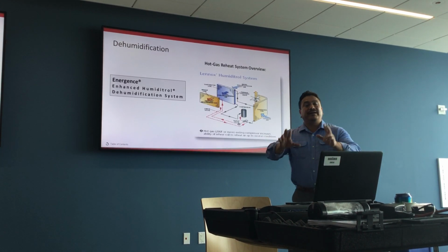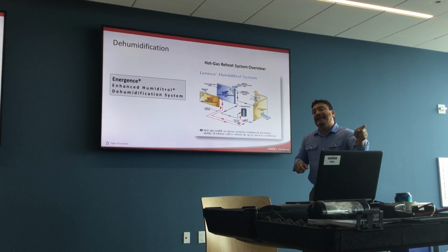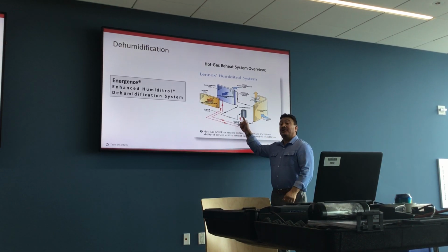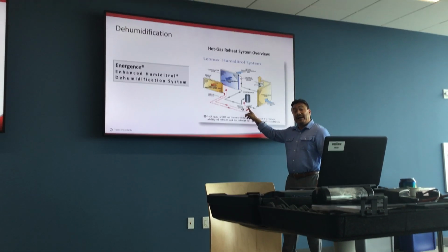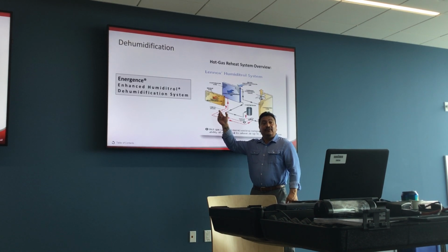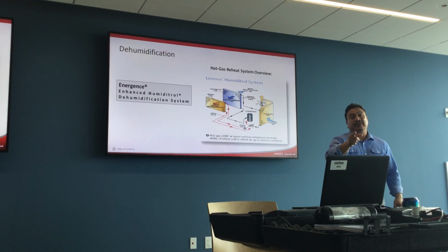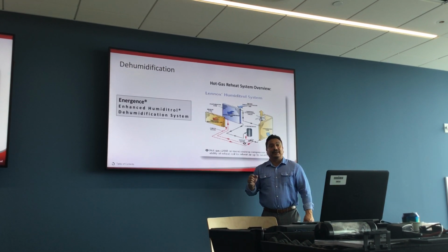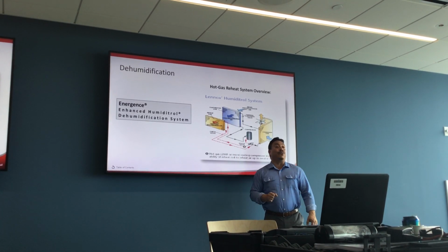we have satisfied the temperature set point in the space, in the event humidity is still too high, the compressor will continue to run, opening a hot gas bypass valve, pumping hot gas into the coil, providing neutralized air into the space, further drying the air out. That is the whole magic behind the dehumidification or reheat coil.